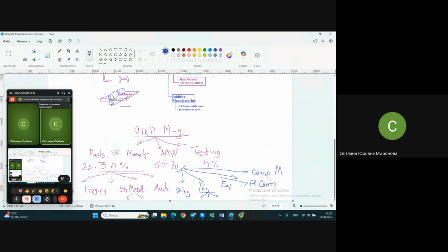It actually looks like assembling when they locate layers of composite with respect to each other, and next finally fastening. But the fastening is of adhesive type, because the binder between or inside these layers polymerizes due to additional temperature and additional pressure in special devices, either an oven or even autoclaves, a so-called pressurized oven. Practically it's more similar to assembly operations. By standard they are parts, but in real manufacturing it's considered an assembly operation.